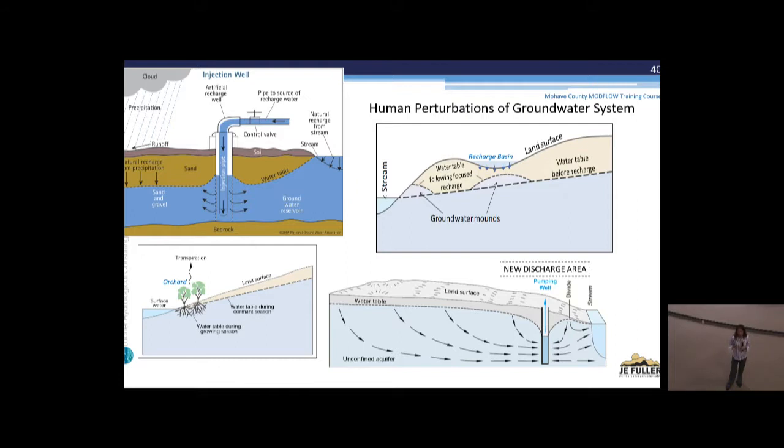This is why effluent is your friend when it comes to recharge, because it's a constant source of water. You never have to turn it off. You might move it over a little bit from basin to basin, but you never have to turn it off. So your mound develops and it just grows and grows and grows forever without succumbing to this intermittent, effluent upward flux, which is very detrimental to a recharge process. Plus, anytime you get drying like that, you build up air gaps in the soil that are difficult to overcome.